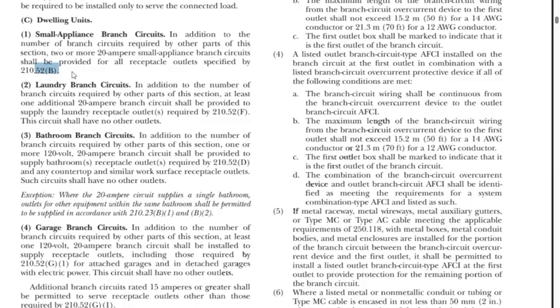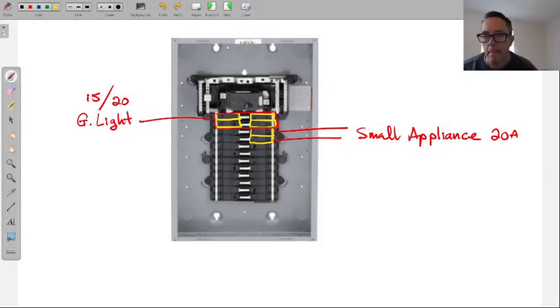There's something here we'll get to later, 52B, but not worried about it right now. If your main panel is stacked out already, and you have a 125 amp main and you're using already 110 amps or something, and you want to add a car charger, you have to not only upgrade the main panel but have them pipe out 200 amps from the utility. Yeah, I just ran into that for some people I knew that got a Tesla and needed a Tesla car charger.